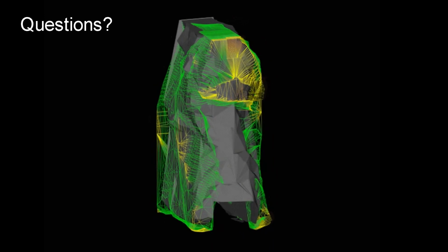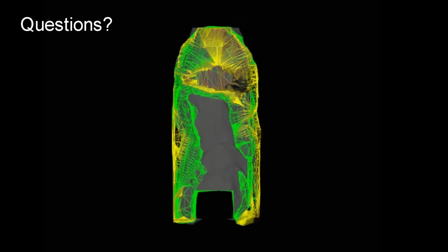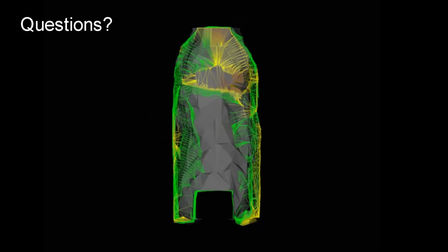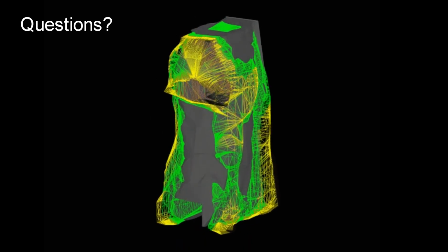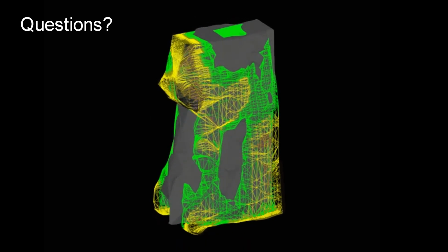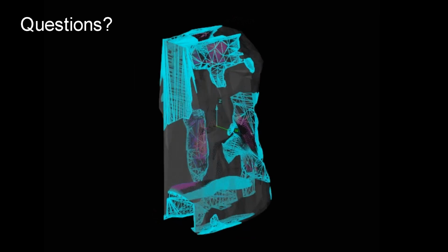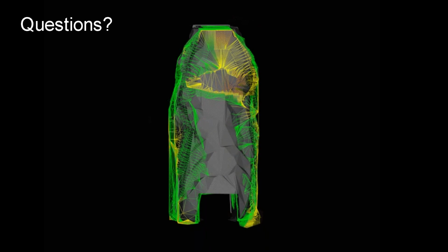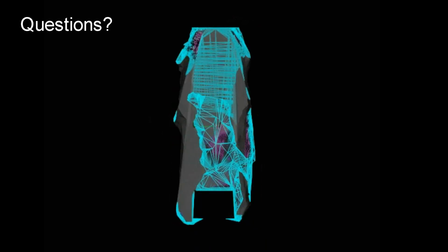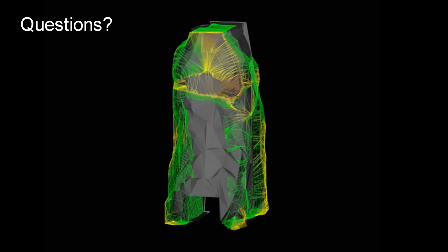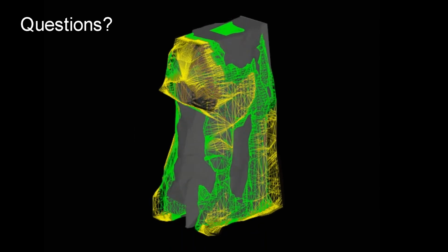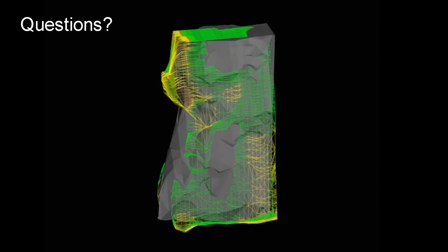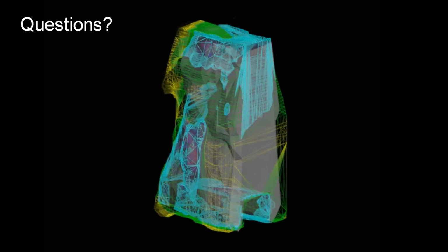Then I've got a question here as well, that some of your comments on the ventilation impacts were missed. Could you just reiterate what those impacts are, Led? Sure. So if we have a continual issue with overbreak, adding that rough surface to our drifts, or having to add additional rock bolts, mesh, steel sets, or anything, that is just going to increase the resistance in the drift that potentially wouldn't be planned for or designed in the ventilation model.